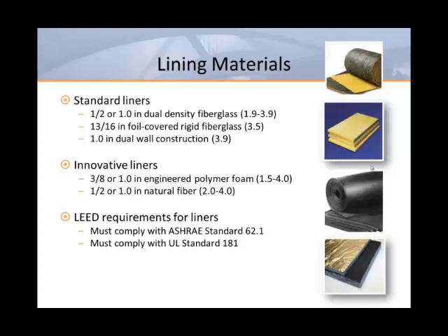Fiberglass has good acoustical properties along with good insulating properties, but many system designers are trying to get away from exposed fiberglass. For critical environment applications such as hospital operating rooms or laboratories, fiberglass covered with foil or dual wall construction is needed to keep any stray fibers out of the airstream.